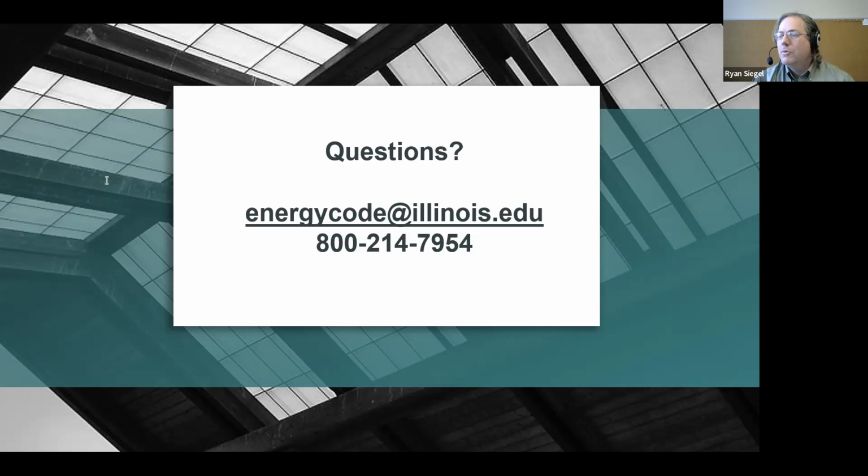We did have a few other questions come in, one of which is checking on the code requirements. What is the threshold for economizer? And that's over in C403.8.5 economizer. So individual fan systems with cooling capacity greater than or equal to 54,000 BTUs per hour, in buildings other than group R occupancy. So if I recall, 54,000 would be 4.5 tons, approximately where that would be.